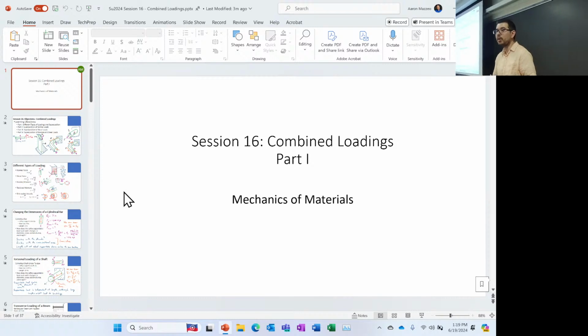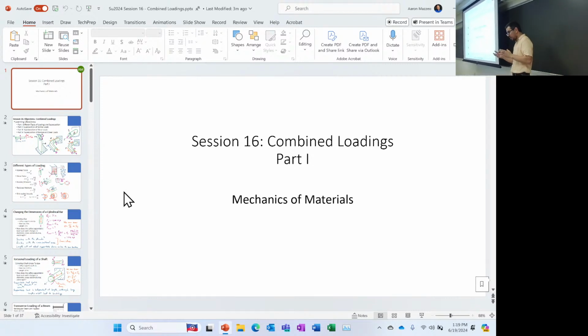That's surface tension, right? Sigma essentially becomes surface tension, because surface tension is joules per area, right? Or it's actually newtons per meter, okay? So anyway, you have this surface tension that causes there to be an even higher pressure, okay? Which means if there's a higher pressure, by Henry's law, the inner surface of the bubble can hold more dissolved air in it than the surrounding liquid.